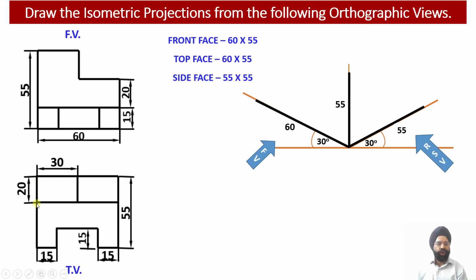So we can see that on the rear side there is a vertical web, and this vertical web is also not a straight web, because in this vertical web again we have a rectangular slot which has been provided on the right hand side of this vertical web. So one rectangular slot is there in the horizontal web which is lying onto the base, and another rectangular slot has been cut in this vertical web towards the right hand face of this particular solid.